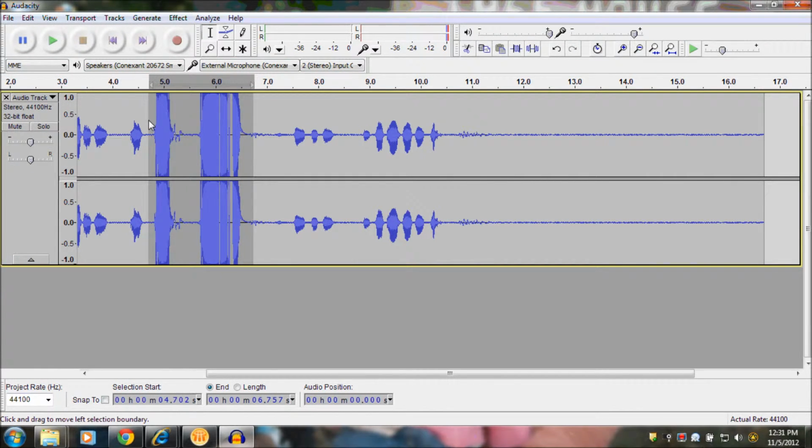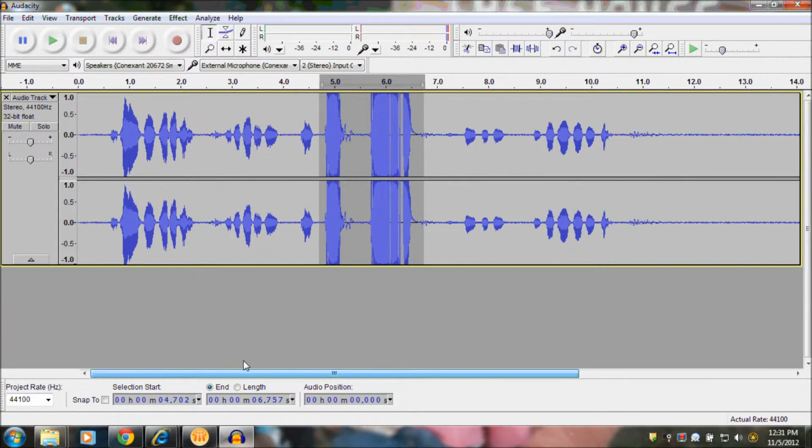First, however, I want to call your attention to these. Here I've clipped the audio by either getting too close to the microphone or having the microphone set too hot. This is going to cause some pretty terrible distortion that's probably going to render this clip unusable. I really want to get the peaks as high as possible without going so far as to square off at the edges. This squaring off of the waveform is known as clipping, and it's what causes distortion.